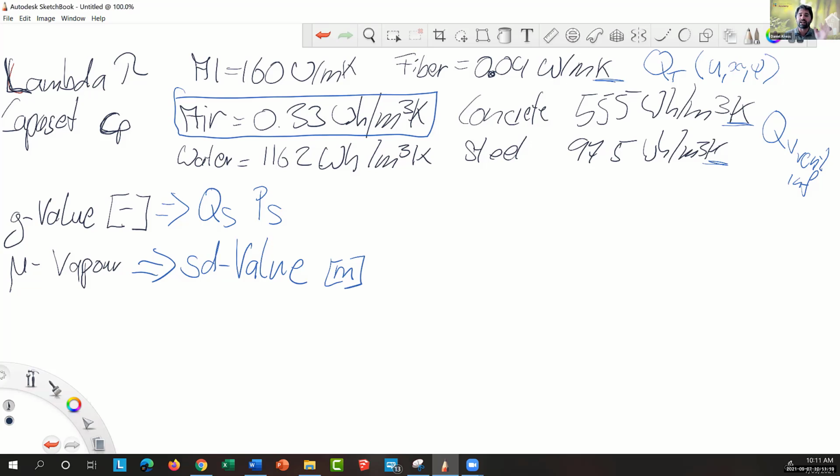And so now the savings of the system is higher in a shorter period of time. And now it's more economical to put a really efficient system in a conventional house and not in a passive house. So the return of investment is earlier in a conventional house that has more losses, because you're able to recover more energy in a shorter time.